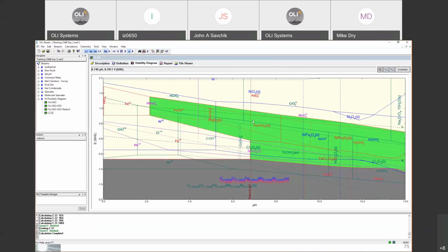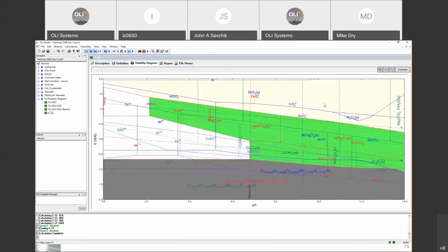then in here it's going to be a little bit messy, I'll say, to understand. So how can you understand this alloy Pourbaix diagram, okay, for this in water? You'll see down here, this is again the alloy, the gray area is your alloy, okay? And now there are a bunch of different colors here, blue, red and purple, and some green color, right? So four different elements here, right? And it's color coded. So anything that is with nickel is blue. Anything that is with iron is red. Anything that goes with molybdenum is purple, and the green, this one is chromium, okay?